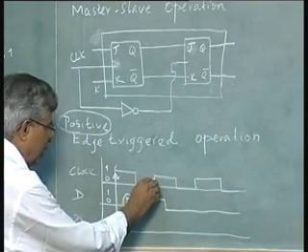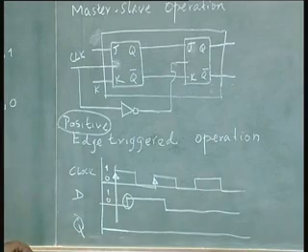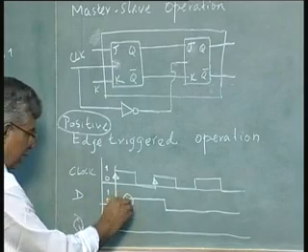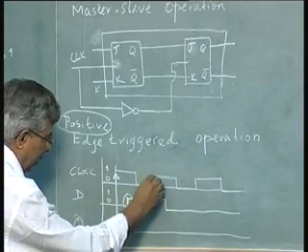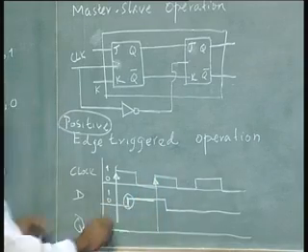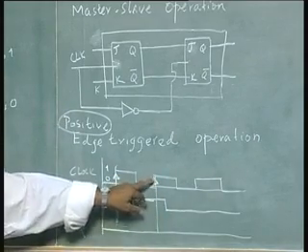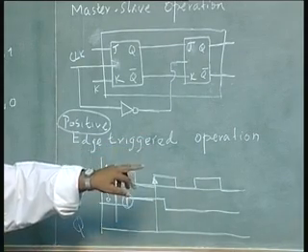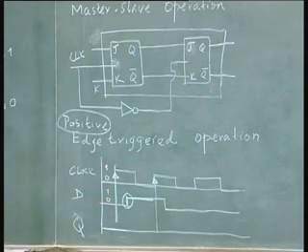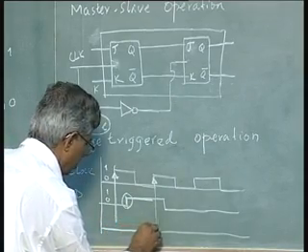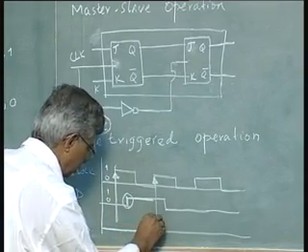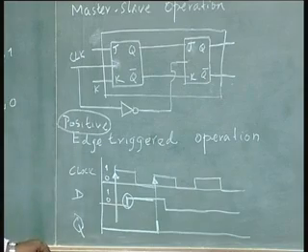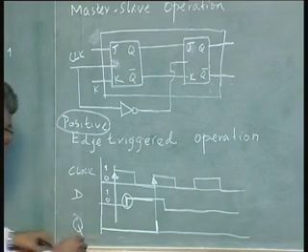Until this positive edge, which is the second positive edge, this input in D will not be recognized. At this point in time, again the flip flop input will be looked at, which is D equal to 1, and when D is equal to 1, the output will be Q equal to 1 for a D flip flop. So this will become 1. Q has become 1 from 0.